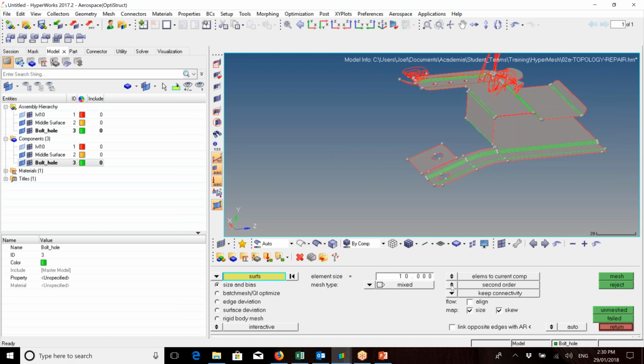If you go to second order, your square, which had 4 integration points, now has 8. There's going to be another point in the middle of each of those lines, same as a triangle. So if you do use second order elements, you need to be aware that, yes, your analysis will probably be closer, but it will take a lot more time because you've got a lot more calculations being performed, which needs to be taken into consideration with every model that you mesh and set up. The more elements and more integration points or degrees of freedom, it's always more calculation to be performed.